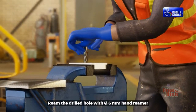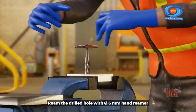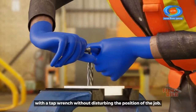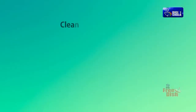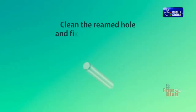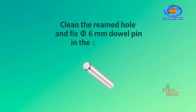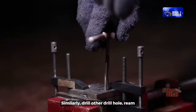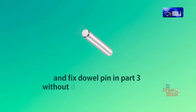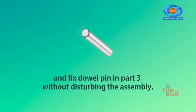Ream the drilled hole with diameter 6 mm hand reamer with a tap wrench without disturbing the position of the job. Clean the reamed hole and fix diameter 6 mm dowel pin in the assembly. Similarly, drill other drill hole, ream and fix dowel pin in part 3 without disturbing the assembly.